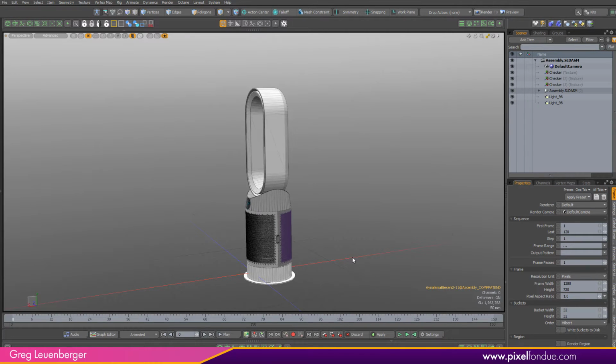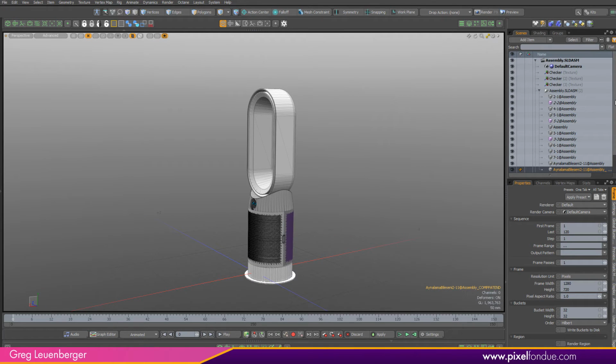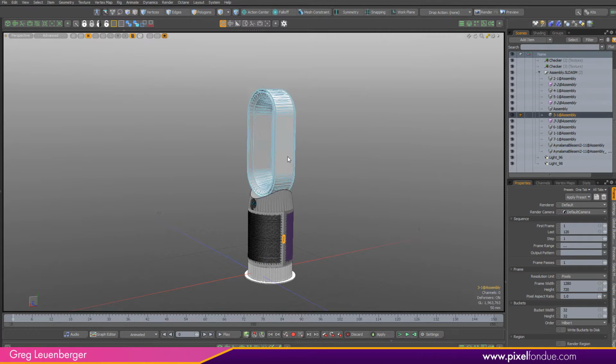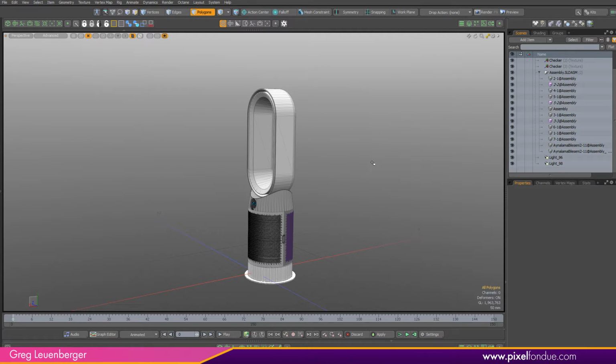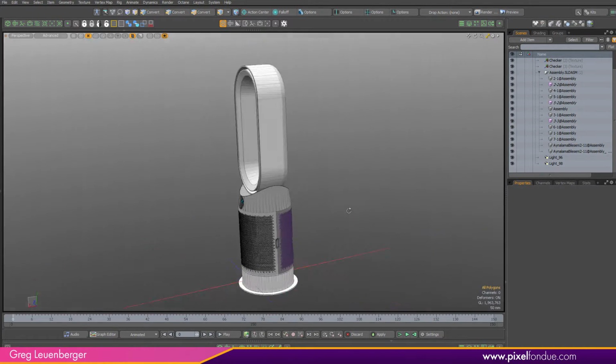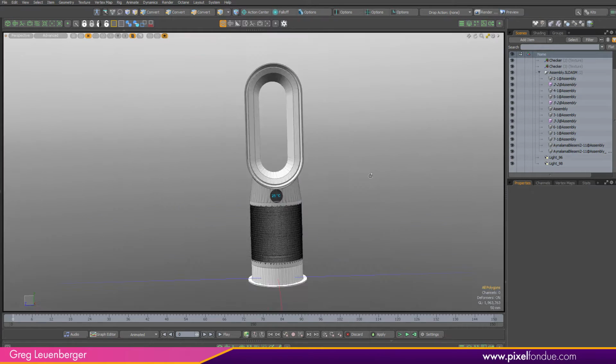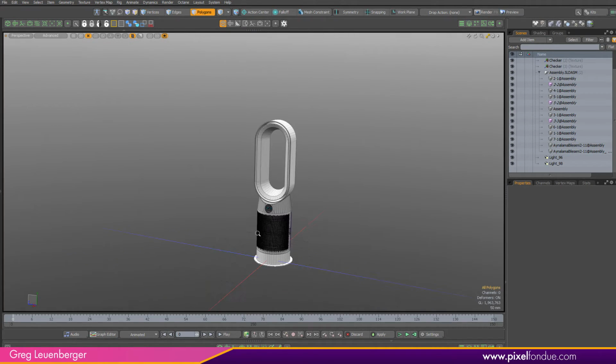We're going to hit OK. All right, here's our air purifier. Let's see what we've got. If I flip open our group here, you'll see again there are static meshes, these gray boxes. So I can't go in here and select any polygons, points or edges and manipulate them, and that goes for UVs too. The idea is that it's supposed to be faster in your viewport. Your mileage may vary. In this advanced viewport, it starts off really slow, but it eventually caches everything, gets it into VRAM or whatever it's doing. It's slow for the first 2 seconds, but then it gets super fast.